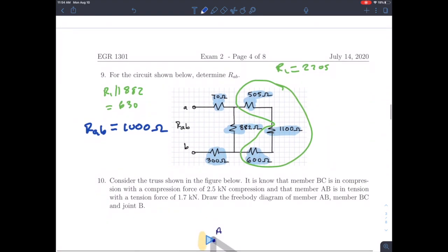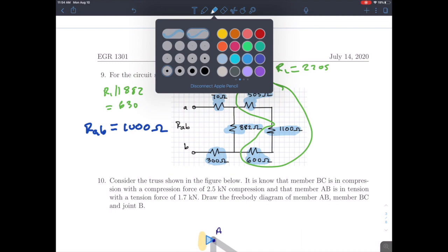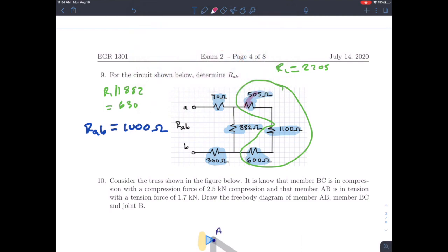All right, let's go through real quickly the workout problems for exam 2. So the first problem is to find the equivalent resistance, and when I'm looking through here, I notice that these 3 resistors are in this same outer branch, so it's the same current flowing through them, so I know those must be in series. So I can add all those together and get an R1.